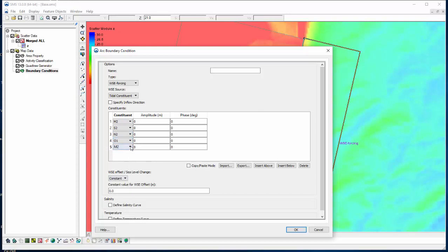And so you would look at the tide tables in your area and choose values here that make sense. So you're given, for every individual area, some amplitudes and phases. Those amplitudes, if they're tiny, have no or negligible contribution, and so you really don't need to specify them. If they have a significant amplitude, say 0.2 meters or 0.1 meters or above, then you might think about including it.